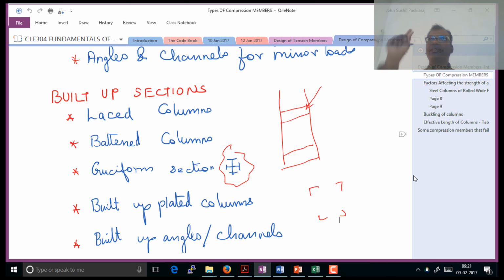To weld thicker sections, you have to use very specialized techniques, because when you weld, the thick section can absorb much more heat. So by the time you get an appropriate temperature for welding, the section might have cooled off, which is a problem. Again, you have what is known as HAZ, heat affected zone. So when you are having thicker sections, all these sort of problems come into the picture. So it's always better to go for smaller sections.